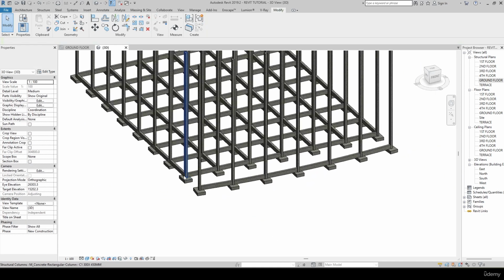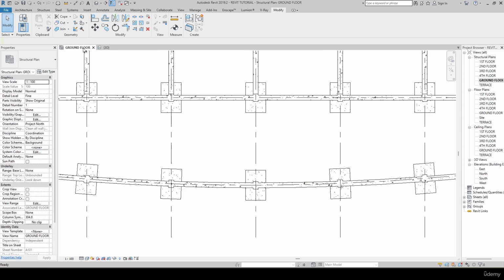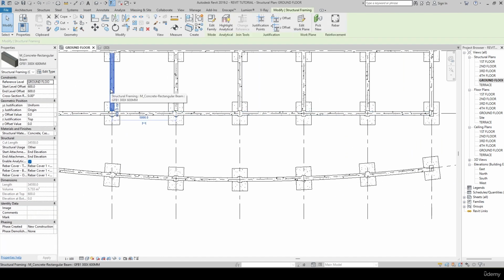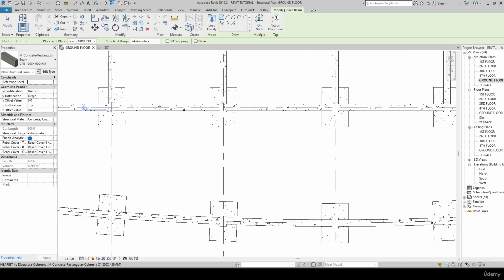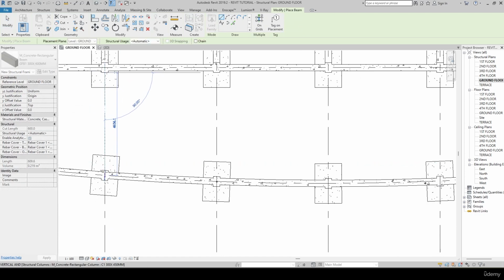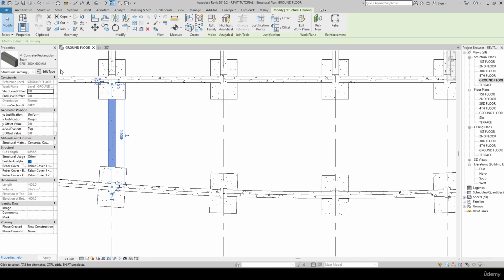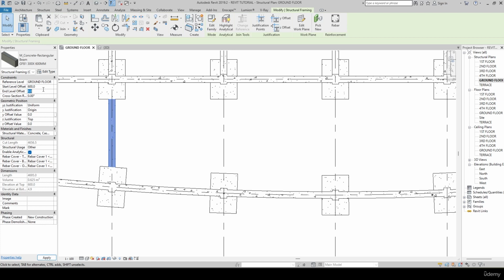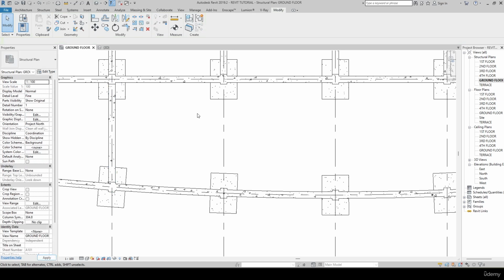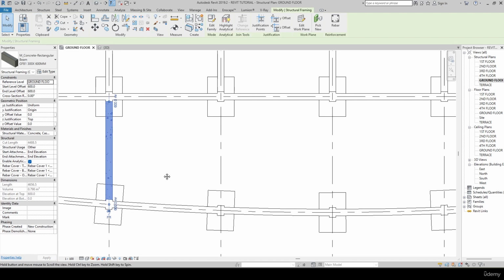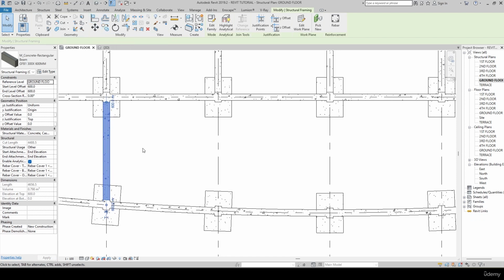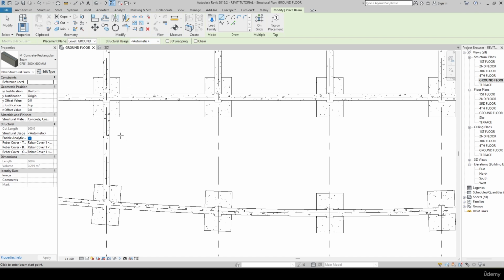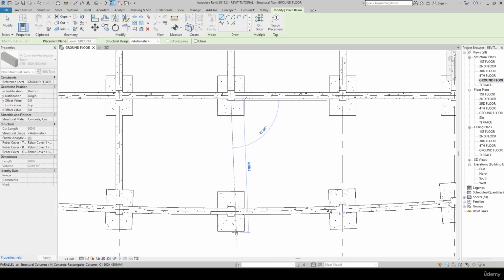Yeah, so now I think I need to connect these beams, that's all. I'll go here, I'll add the beams once again, CS, connect these beams with here. Okay, again I'll take this 600 mm as the offset, again 600 mm. Okay, fine. I'll keep as the CS thing, and I add the beams from here to here, again from here to here.